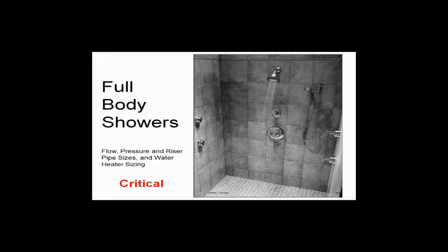We just allowed 6 total for the bathroom. You come along and put a full body shower in it, you're going to be short of water if that's what you used. And if you're doing the plumbing design, if you're picking the pressure booster, you best know what kind of showers are going in your apartments. As to whether they're legal with the city or not, I'm not going to pick that battle.